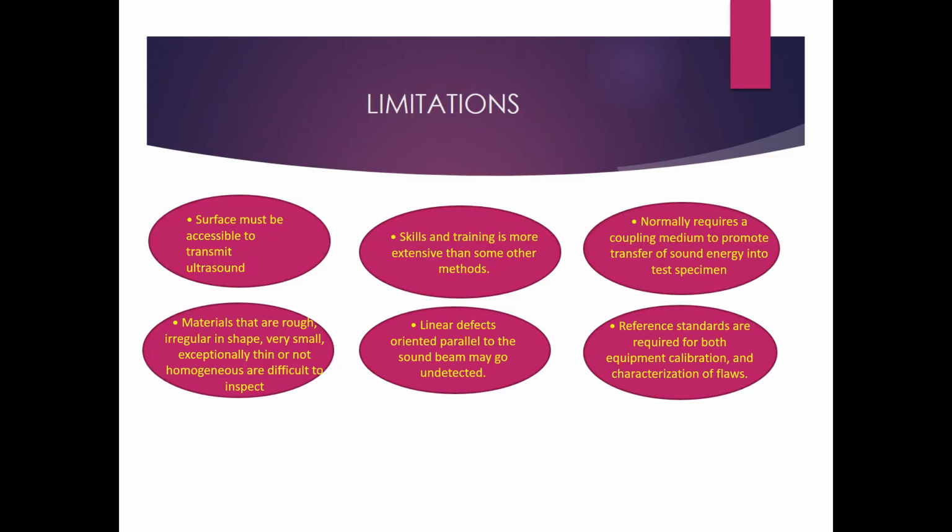Last but not least are the limitations of ultrasonic testing. The first one is that the surface must be accessible to transmit ultrasound. Skill and training are more extensive than with some other methods. It normally requires a coupling medium to promote transfer of sound energy into the test specimen. Materials that are rough, irregular in shape, very small, exceptionally thin, or not homogeneous are difficult to inspect.